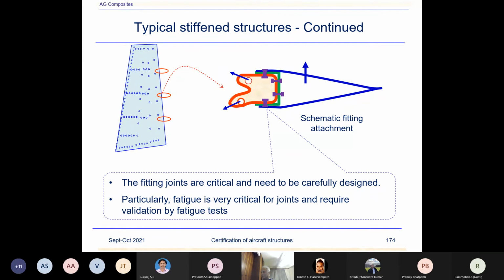Okay, sir. Fine. Thank you. Normally we don't find variations. Once you have decided the allowables, you are not testing the materials for those allowables every time. They are logged in, and you assume that the material allowables are mapped to the material which you are using. You don't keep on testing. It's only the acceptance test, only a few tests, not heaps of data.